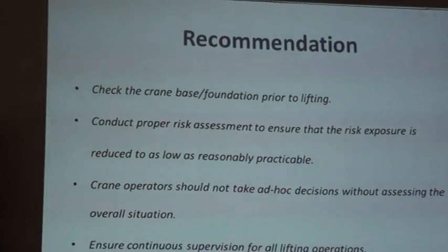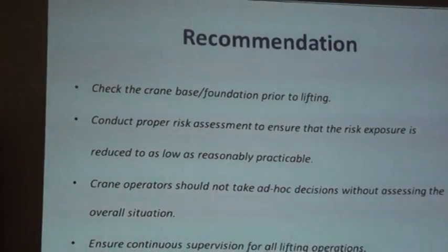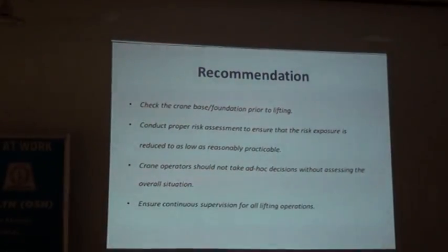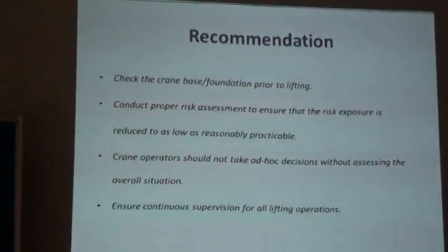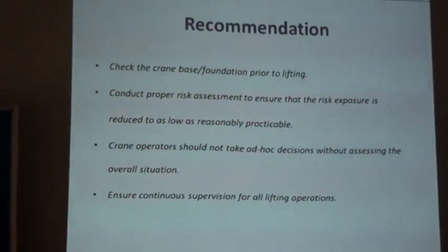Check the crane base and foundation prior to lifting. Conduct a proper risk assessment to ensure that risk exposure is reduced as low as reasonably practicable by the rigging scheme. Crane operators should not take ad hoc decisions without assessing the overall situation.